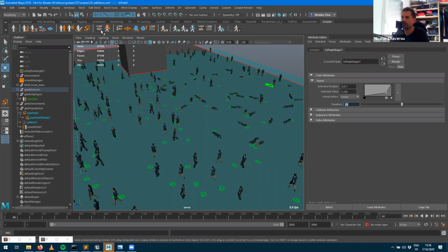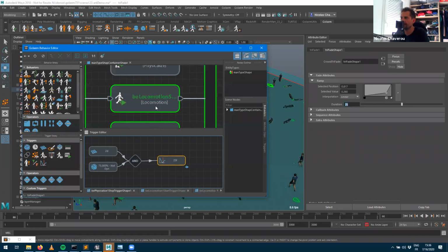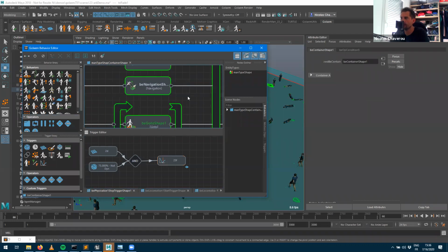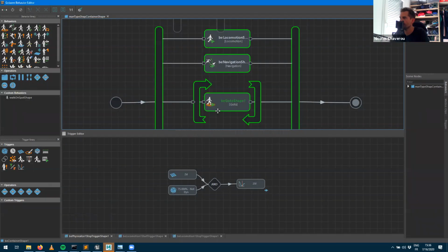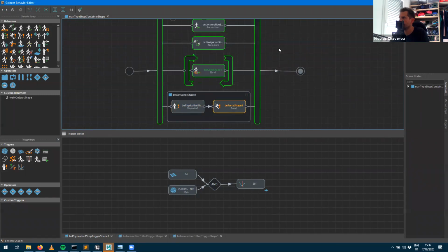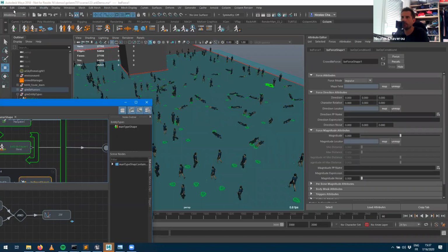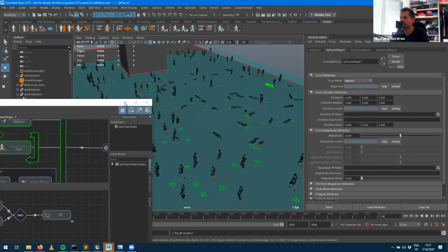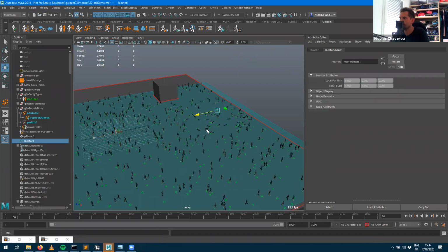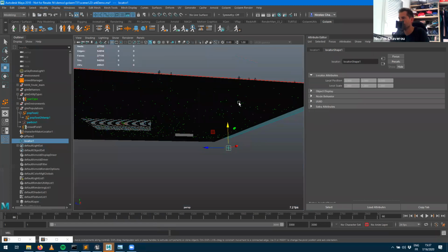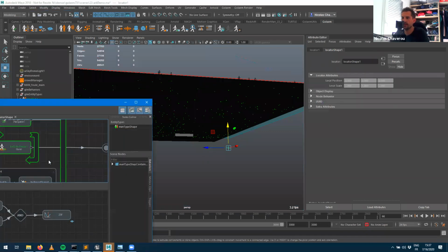Okay, great. I promised that those guys will fly, so let's make them fly. As soon as I turn them into physics mode, now I want to apply a force to them. So I'm going to put a force behavior next to those. Let's zoom that down. First turn into physics, then apply a force. And the force can come, maybe, from a locator. So I'm going to quickly create a locator in the scene, which is here. I'm going to put that below the ground, so the force will come from below. That will bring my characters up. And I'm going to connect that to my force behavior.